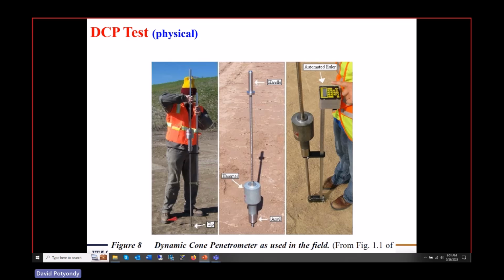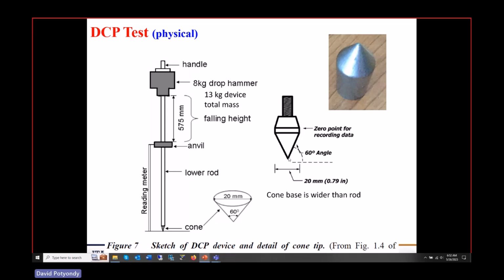Then just quickly to show again the kinds of stuff you do with PFC, we modeled this, which is called a dynamic cone penetrometer. It's a way that when they actually lay down the aggregate base, they can in situ measure the stiffness of this thing and the strength of this thing. So it's just a big heavy weight that gets dropped and they look at how far it goes in, right? So this is the tip of that cone penetrometer. This is a steel thing. It looks like this, right? So we said, oh God, we got to model that in PFC.